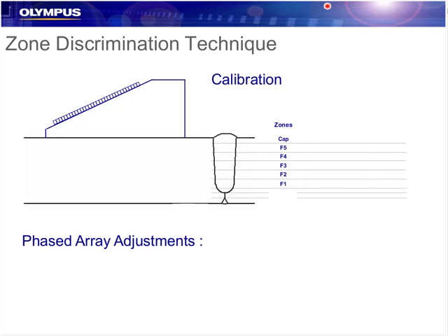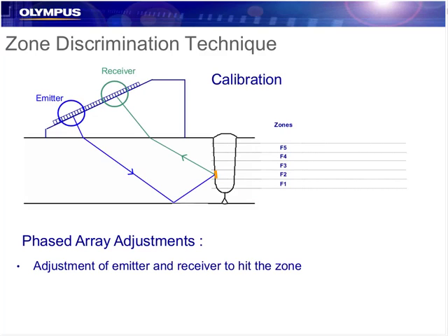And then what we can do is basically, instead of using a group of elements and doing a pulse echo technique where the sound comes back to the same group of elements like we would with an omni scan or a sectorial scan, we can actually use a pitch catch technique. So this is a very similar probe. In this case, we often use a 60 element probe.